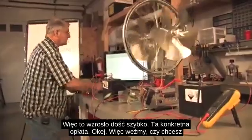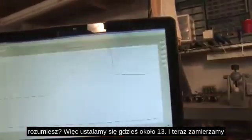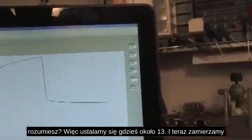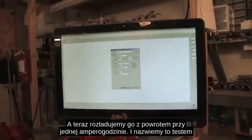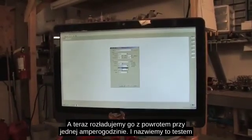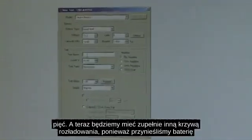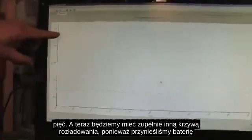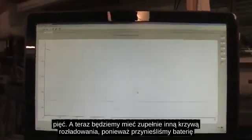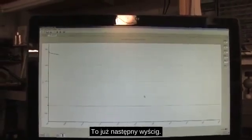Okay, so let's take, do you want to catch this? So we're settling out somewhere around 13 something. And now we're going to take the amp hour, 13.94. We're going to take this, and now we're going to discharge it back at 1 amp hour. And we'll call this test 5. And now we'll have a completely different discharge curve because we brought the battery up higher yet.